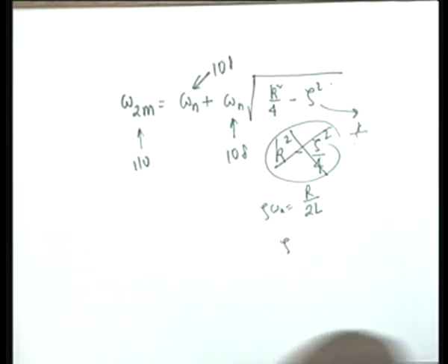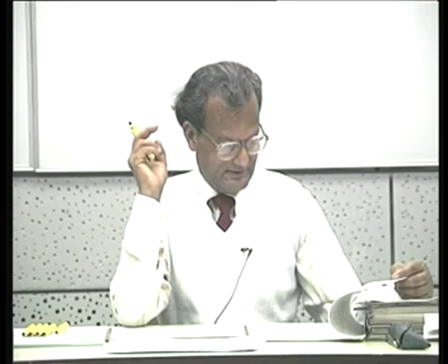Well, the other way is, if you remember, in a single tuned circuit at current resonance, that is when the current is maximum, the voltage across either the inductor or the capacitor is Q times the applied voltage. Did you know this? No, sir. Okay, it doesn't matter if you didn't know it, but now at least you should know it, and it's very simple to prove.